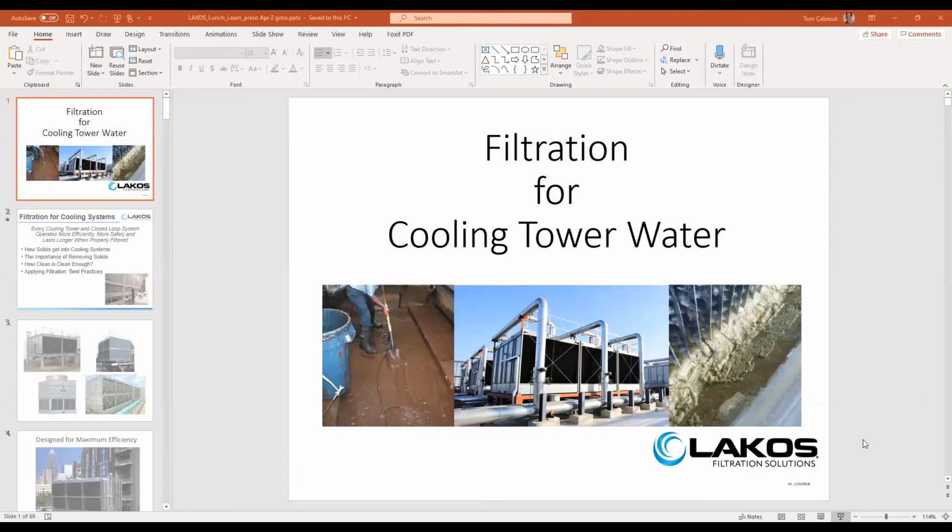The TC package is just a great replacement for it. The only thing I warn you about is, you know, watch your horsepowers. Electrical will be the most expensive part of the installation, so that's one area that you need to focus on. The Lakos systems have such powerful pumps. Don't be afraid to match horsepower and maybe look at your pump curve, overstate your flow a little bit to get the customer taken care of, but keeping the installation costs down.